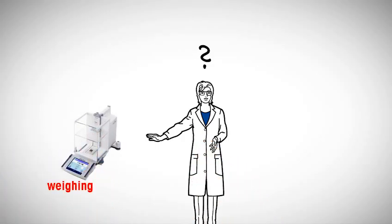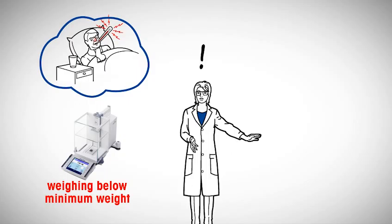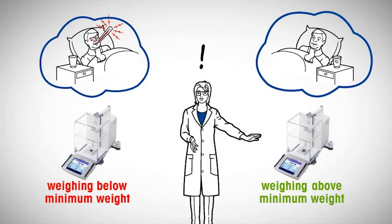Establishing the minimum weight of a balance is a simple and effective way to avoid weighing errors. You may think of the minimum weight as the accuracy limit of a balance. As long as you weigh above this limit, measurements are sufficiently accurate. It is important to note that USP now also gives recommendations on how to establish the minimum weight for applications outside of USP 41.